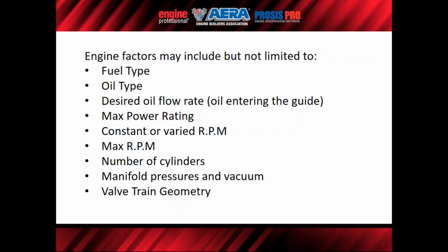One time I remember a Federal Mogul engineer that designed crankshaft seals talking about how, with all the oil changes, basically every year there's new changes. That's why they just try to throw the highest level materials at it. So they're not dealing with, well, this oil supply has this additive pack and that one has that additive pack. They just try to go for the highest level. But oil does have a huge impact on the effectiveness of any material used for a seal.